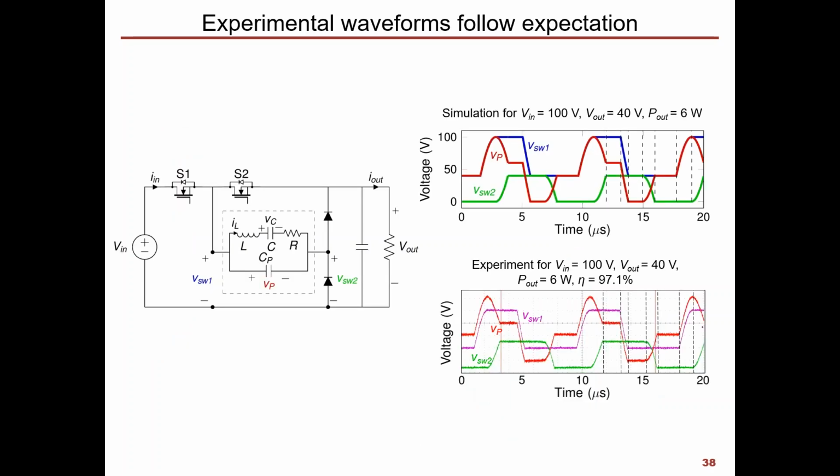Now, when we operate this piezo-based converter experimentally in the real world, we get waveforms that match very closely what we hope to see. This is great news for being able to operate these piezo-based converters with the high efficiency behaviors we want. With these behaviors, you see soft switching, which means the 2 switch nodes have resonant transitions between their low points and high points. So you see VS1 and VS2 slowly resonate up to each of those for 0 voltage switching.